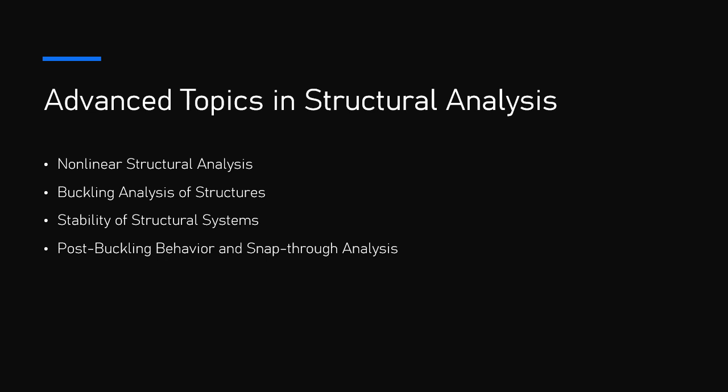3. Nonlinear finite element methods, FEM. Nonlinear FEM is widely used to model complex structures subjected to nonlinear behavior. The finite element method, FEM, is modified to account for material, geometric, and boundary nonlinearities. The nonlinear stiffness matrix changes at each step of the analysis, and the solution procedure requires updating the matrix as the structure deforms.